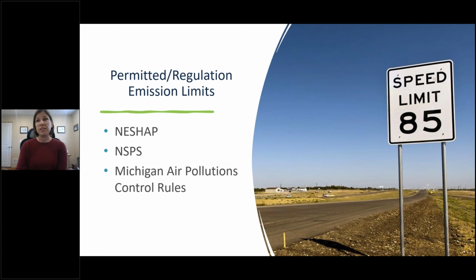These emission limits can be used to determine the allowable emissions from the emission units that are subject to the standards. One example is the engine NSPS. Emission limits in grams per horsepower hour that engines are certified by the manufacturer to meet. If you know you will buy a certified engine, but don't know which engine, you can use the max emissions allowed by the NSPS to do the calculations.